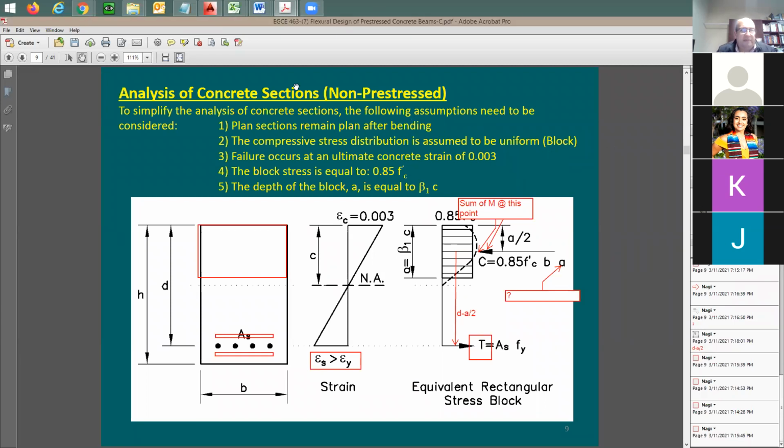So good. I mean, it looks simple for conventional concrete. At a certain point also, I need to confirm that the steel is really yielding, and I need to figure out the phi factor. So usually we consider the concrete to be failing at 0.003, and from these 2 similar triangles, I should be able to figure out the strain in the steel. Once it goes beyond the yield strain, and how much is yield strain? Can someone help me with this? How much is this?